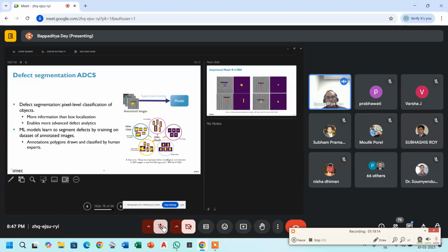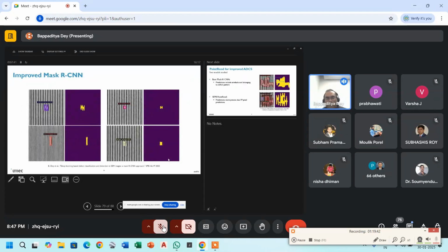So this is helpful for the root cause analysis of what physical properties have changed within the tool or the recipe, or why the tool has drifted in the hardware part that is originating this defect. So this kind of metadata is important to reverse engineer the process steps for the process experts or the tool experts. And that is how we are going to help them with this segmentation method. So you can see that you have plugged in an image, again at the nanometer scale, and the neighborhood is not important for us. In which region, and what extent of defect has appeared in which nanometer scale range bandwidth is more important to us, okay? And we are precisely generating the segmentation for them.